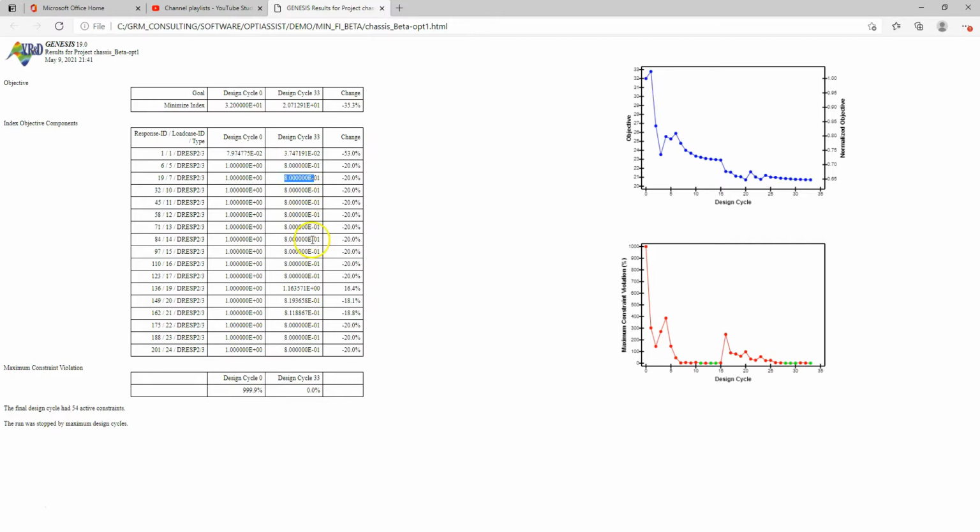So you can see that in most cases the design variable has been moved down to 0.8. Down in these side push cases you can see clearly that load case 19 is the one that has worked the hardest, and it's found that there's a trade-off between weight saving in the current geometry and failure index. It's saying, I'm better to just compromise this failure index a little bit for the benefit of getting this good and efficient mass. And that allows you to understand that that is a driving force in the optimization, and therefore you can maybe look at geometry changes to improve the structure in there in a more efficient manner.